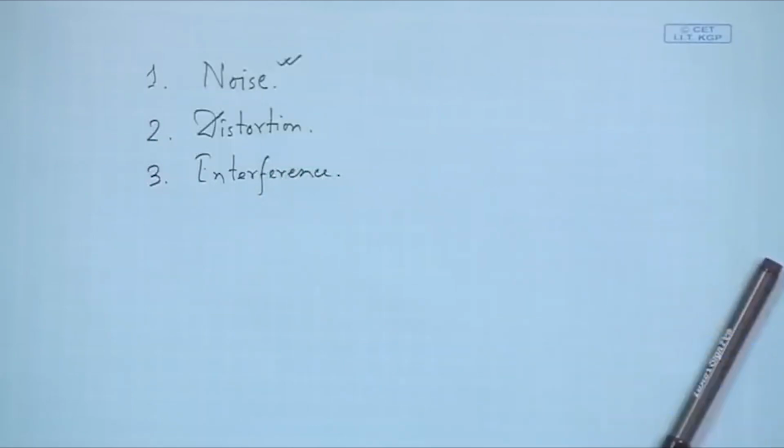So what is noise? We are trying to transmit an electrical signal which is being converted into electromagnetic wave, and in the channel, due to different reasons, there might be random electromagnetic waves which can be added to this transmitted signal. So we generally characterize the channel as an additive channel. What do we mean by additive channel? As if it's a simple adder of signals. Whichever signals we put as input to this channel, if there are multiple such signals, it will just add up those signals.